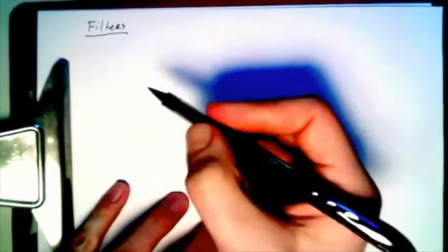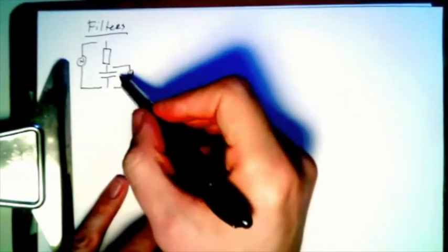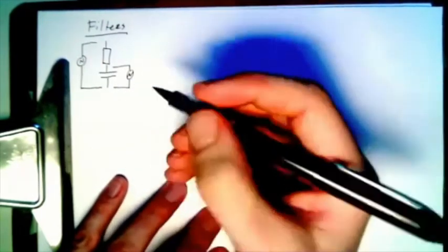So remember when we started, we had this filter that we had analyzed, and we were measuring the voltage across the capacitor as a function of the AC signal and frequency that we were applying to the resistor and capacitor. And I said, this is a low pass filter, because at low frequencies this thing is passing, and at high frequencies it's not working. So this is a low pass filter, but now I'm going to draw this a little bit differently.